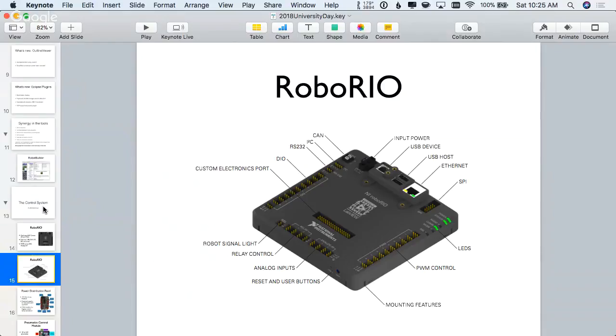So one way sometimes people put stuff onto the RoboRios is they put stuff on a flash drive on their laptop, and they plug it in here and copy it. There's a USB device port, so you can take a USB cable, put one end in there and the other end into a Windows laptop. You can use that instead of a network connection. It's sometimes easier to connect with the USB port than using Wi-Fi or the Ethernet connector.